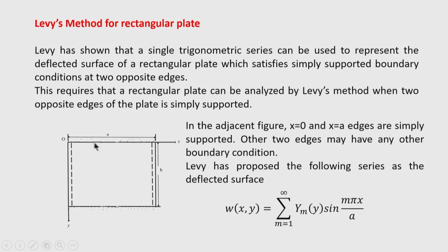The other 2 edges, y equal to 0 and y equal to b, may have any other condition. I have not specified it. The condition will be imposed to evaluate the constants of integration, which we will see later on. So, you have seen that at x equal to 0 and x equal to a the plate is simply supported, and therefore Levy proposed a solution w(x,y) as a single summation of a function of y, called capital Y_m as a function of y, times sin(m pi x by a).